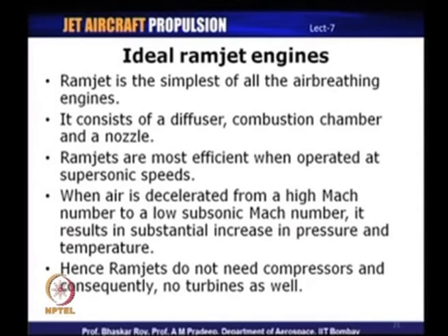There is a substantial increase in the pressure and temperature, and if that is the case, you do not really need a compressor, because the air is getting decelerated anyway without using compressors, and there is an increase in pressure and temperature. With the pressure and temperature already raised, you do not need a compressor, and since you do not need a compressor, you do not need a turbine either, because a turbine is basically meant to drive a compressor.